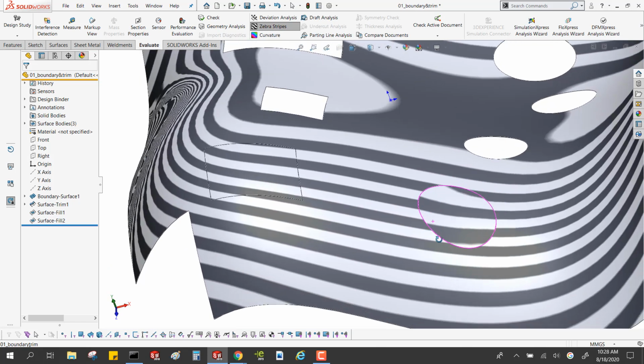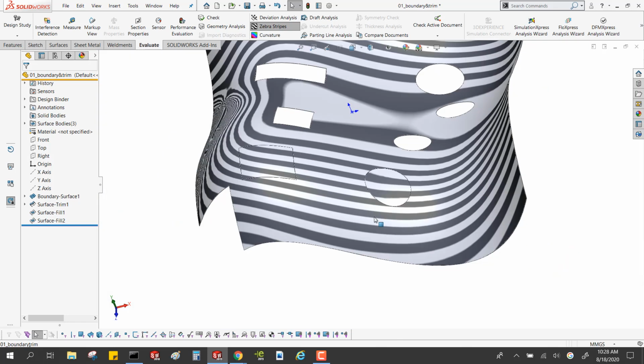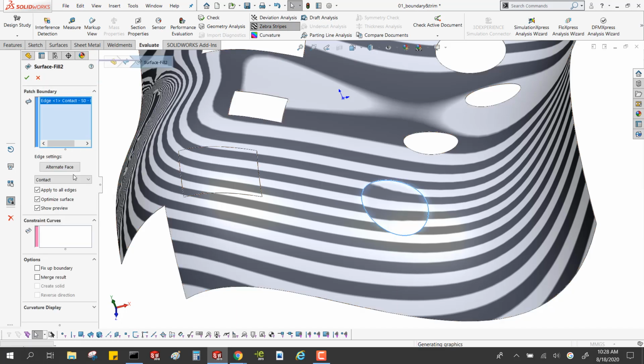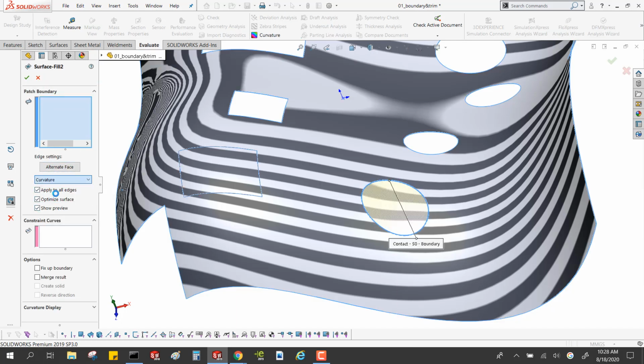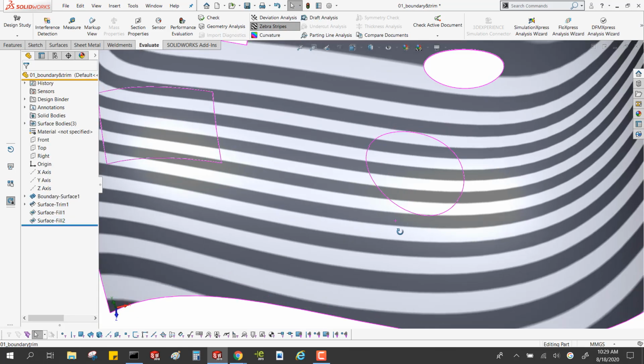They used to put the car that they were modeling, the little clay car, coat it with a shiny metal and then put it in a room full of lines and see if they had any of these non-tangent edges, because they were trying to get a nice smooth surface. Same thing with planes. So that's where we're getting the zebra stripe choice from. But I can really see that I've got some problems here. If I go into the surface again and change it from contact to curvature, I get a lot closer to the real thing.